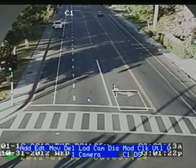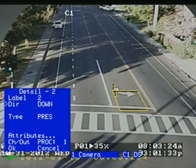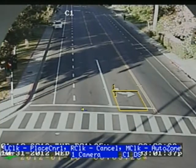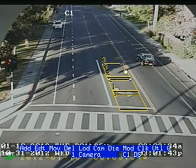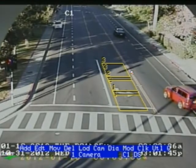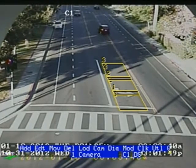To copy a zone with the menu open, if the zone is yellow, place the cursor inside the zone and left click. If the zone is white, move your cursor to Add on the menu and left click. This copies the settings of the zone. Move the cursor to OK and left click. Each time you press down the wheel on the mouse, the system will place a zone above the one you copied. We would not want the zone this close to the lane line, so this one will have to be adjusted. Once you have completed all the zone adjustments, remember to quit and save your work.